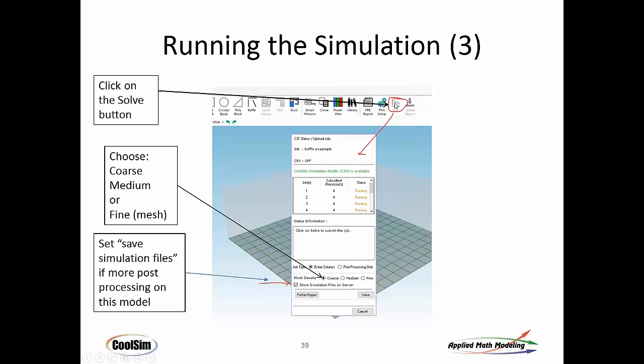When you click Run over here, run means run the simulation, of course, and you'll get an interface that looks like this one. And the number of jobs you can run and the number of processors you can access is a function of your subscription. For many of you, it's just one job with one core. But if you have a subscription that offers more, we can run each job in parallel if in fact they're big. And Fluent is fairly linear in its performance, so as the number of processors grows, the time to solve it declines as a ratio of the number of processors, inversely proportionate, as long as your mesh is big enough, I should say.